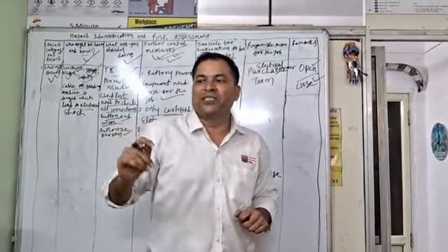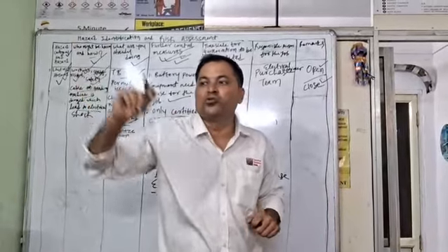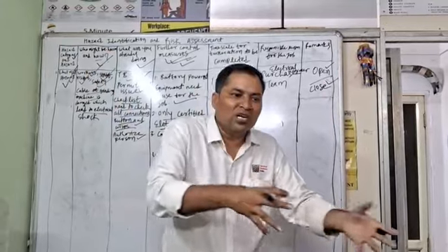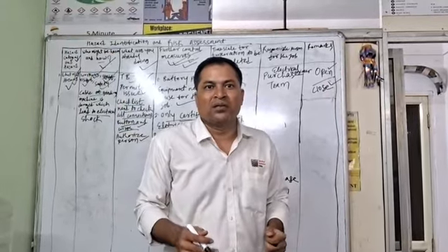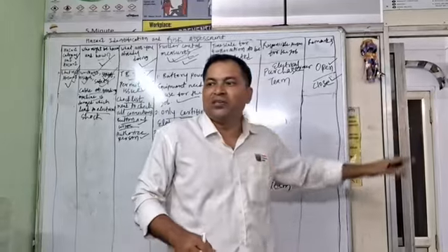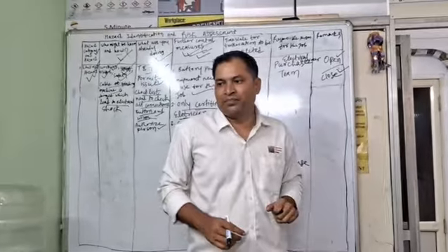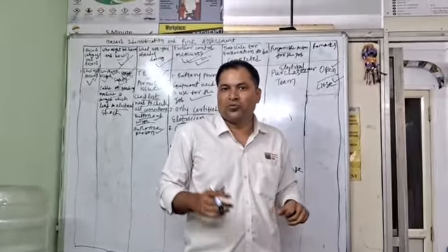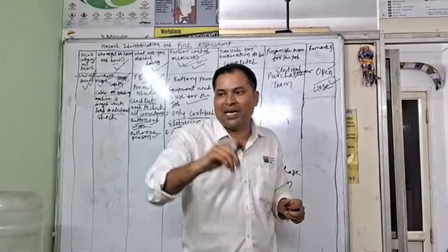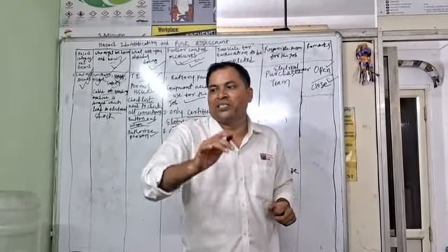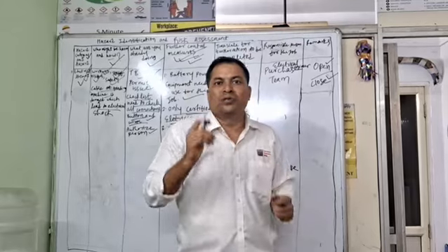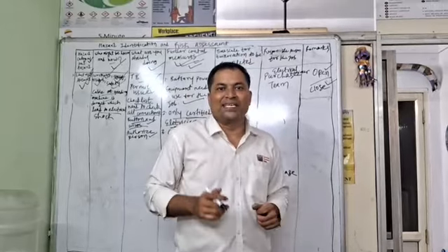So if we have MCCBs, RCCBs and anything goes wrong in the machineries while workers are working, they will get shocked, and at the same time the ELCB or MCCB will trip down. Understood? That kind of thing you need to apply as further control measures, and it will reduce the chances of incident or accident.